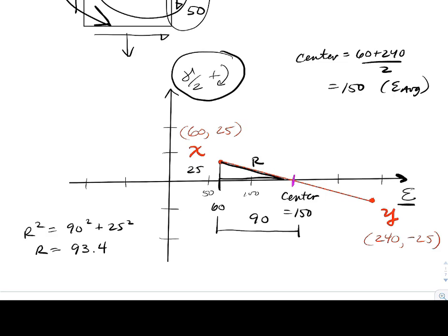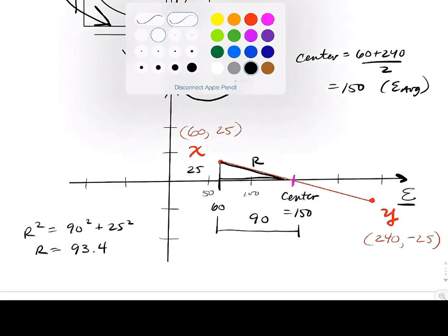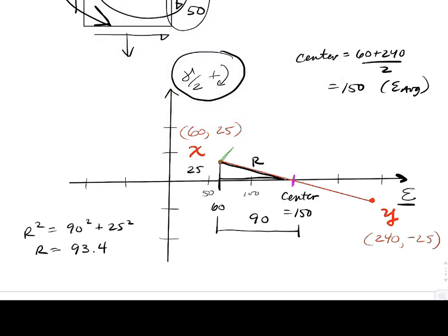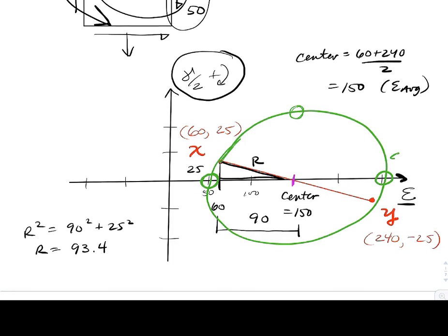So we just go back to our picture, and if we were to strike that whole circle, there's a principal strain, there's a principal strain, and there would be an in-plane shear strain. So at the moment, we're going to call this epsilon max. We're going to call this epsilon minimum.